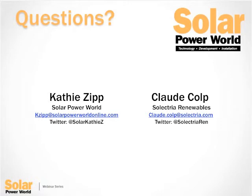Excellent. Lots of questions about the Arcom here. So we'll move to another one. Do the Arcom boxes have residual current monitoring capability? No, they do not. So that portion of the code is new for 2014, and some of the central inverters have that built in as an option too. Basically, for people that don't understand what residual current detection is for, it's actually to combat what's called the ground fault blind spot. Now, the ground fault blind spot happens when the current flows between our negative conductor and ground, and is not detected by our traditional ground fault detection circuitry. So our 500 and 750 XTM have that as an option that you can purchase.